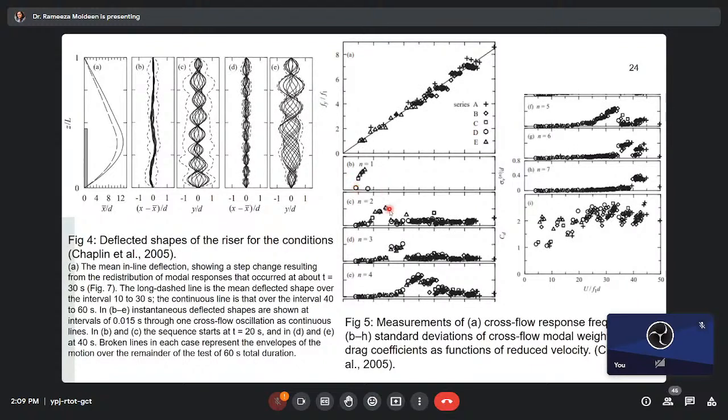So these are the mode shapes. In this experiment, the mode shapes are measured at distinct velocities, so that we can see, from one mode shape to another, how the amplitude is increasing. Up to 7 mode shapes are created. And then finally the drag coefficients are measured and codified. This drag coefficient will help us use the theoretical formulation and find the forces.